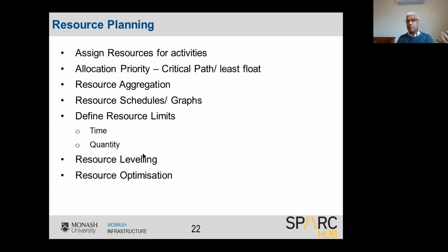You can use the programming software, either MS Project or Primavera, to do the resource leveling. When you do the resource leveling, you do the resource optimization based on the critical path. So you can't delay the critical path. You keep the critical path with the resources and delay the other activities so that the 15 electricians can be divided between the activities. That is the idea. I'm not going to explain again in detail. These are the important considerations when you do the scheduling and the resource management.